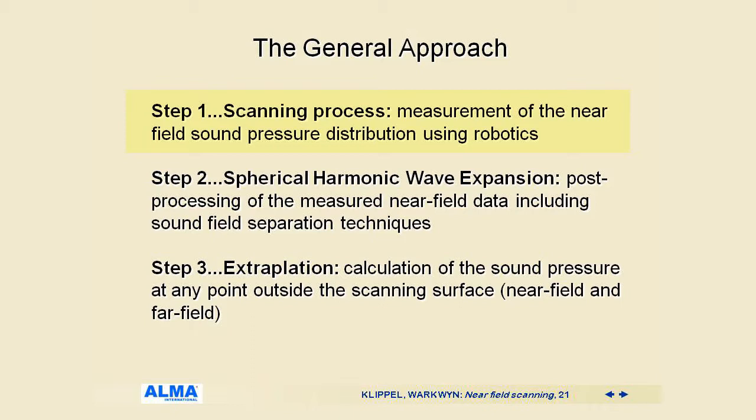The general approach. Step 1, we measure the near field sound pressure using robotics. Step 2, we do a spherical harmonic wave expansion. Post-processing of the measured near field data includes sound field separation techniques. Step 3, extrapolation. Calculation of the sound pressure at any point outside the scanning surface, both in the near field and the far field.